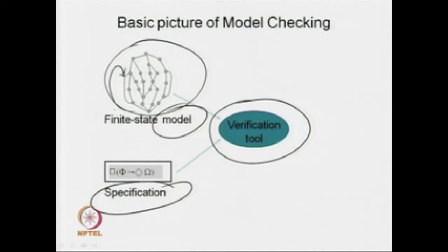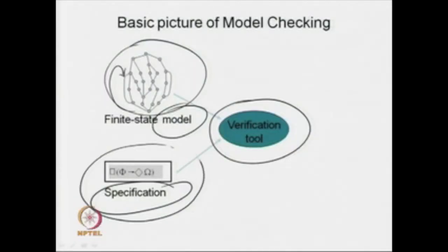Say we are going to design some controller or some circuit. First of all, we have to capture this design with the help of some model. We will see in what way we are going to capture it. After that, secondly, I have already told that model checking is nothing but property verification. Somehow we have to specify our property. So, in some logic notation we have written something and we have said that this is the specification we have given to it.